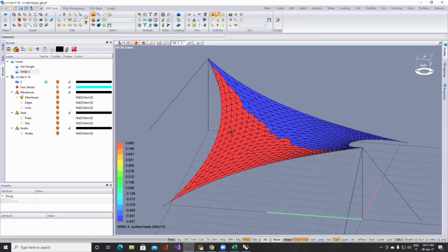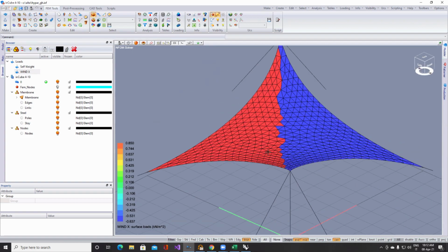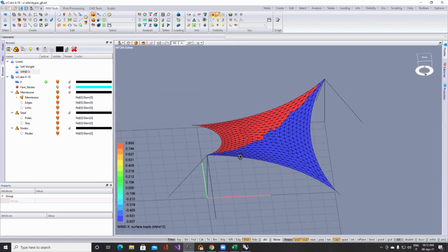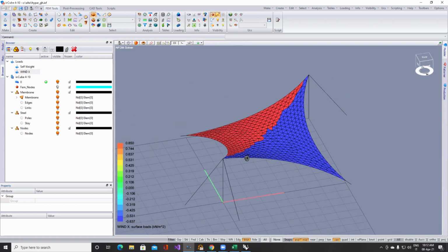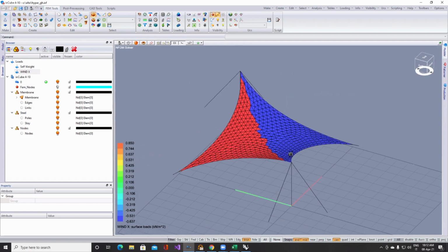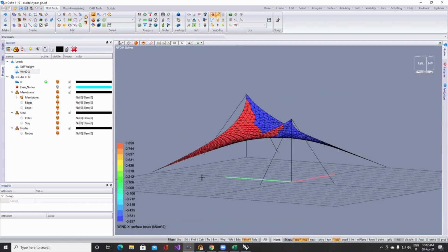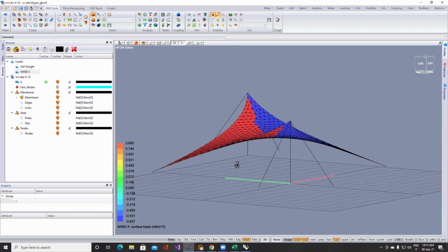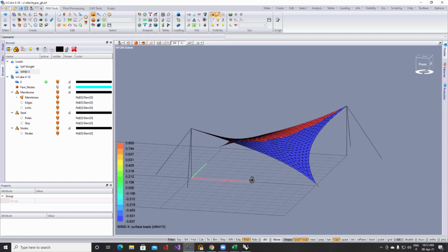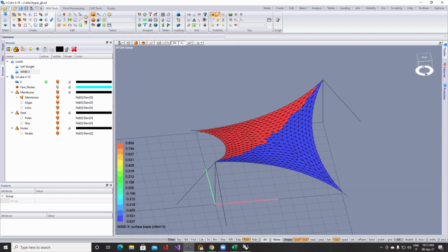Generally a positive CP value will push on the surface. A negative CP value generally is a suction, will pull the surface. So all the different CP values that we evaluate will generate these pressures and suctions. And clearly, in the norms, we'll find out if the surface is open so the wind can go inside, and we will have two CP values, CPE and CPI, the external and the internal wind pressure. And generally, we have to sum them to get the overall pressure on the surface. Okay, so we can say.